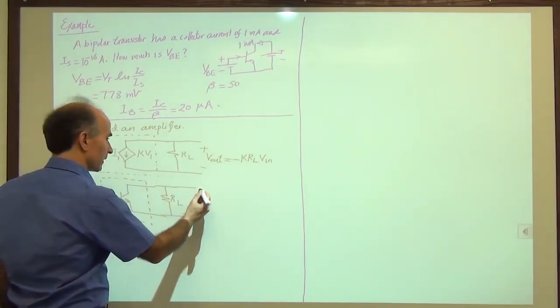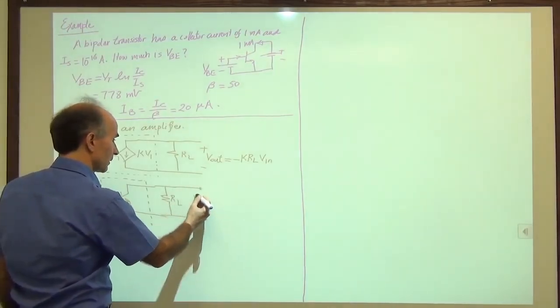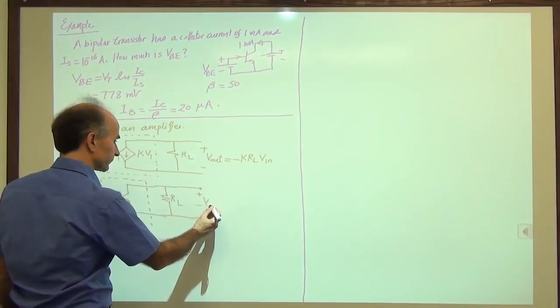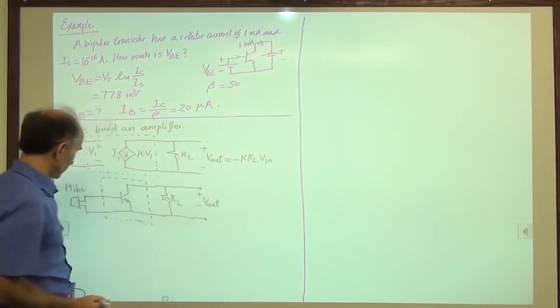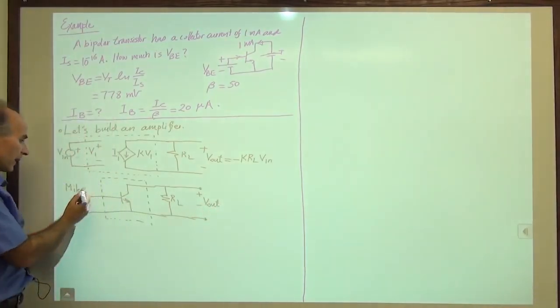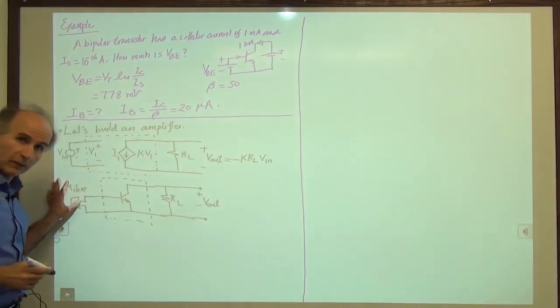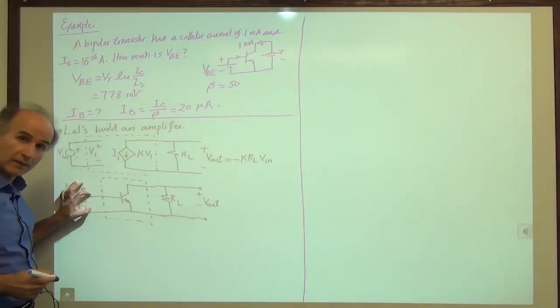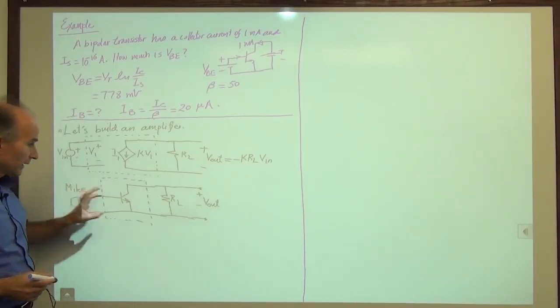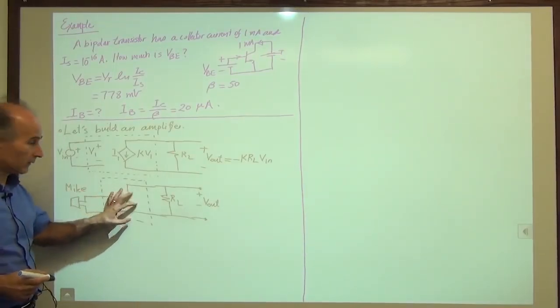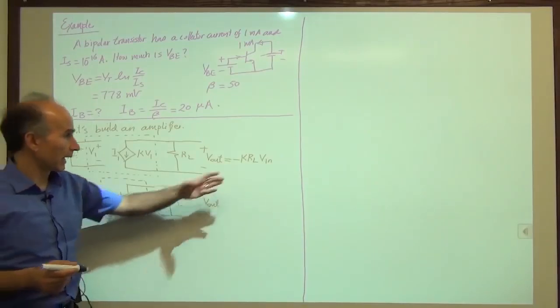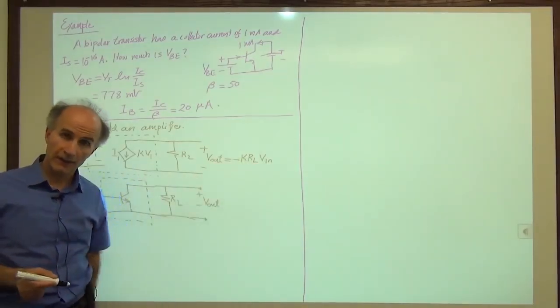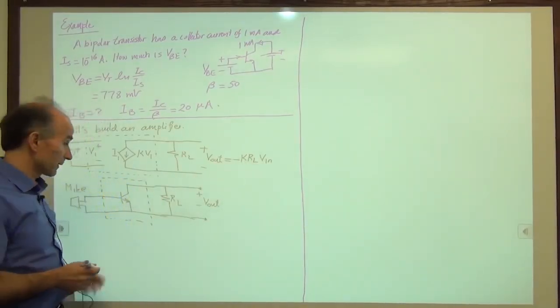And now we go ahead and measure this voltage. So I'm hoping that as my voice goes to the microphone and generates a small, weak signal here, this transistor will amplify it, will deliver it to RL, and like before, we get something large at the output. So let's see if that works.